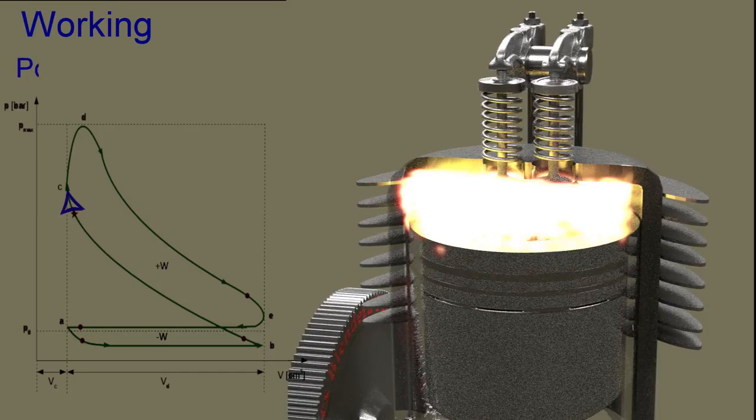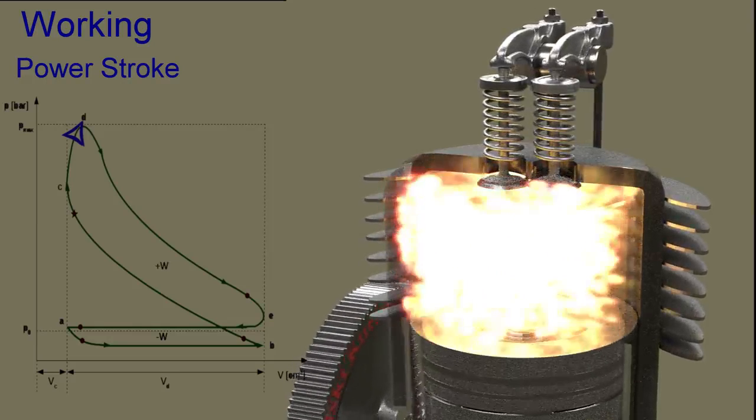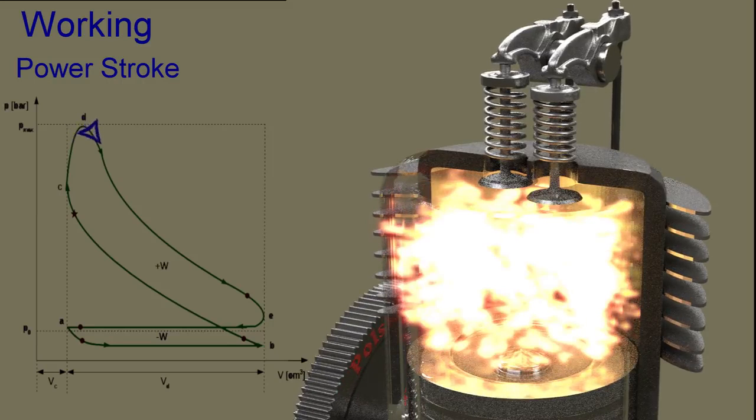Unlike the diesel engine, the combustion process in spark ignition engine is for very short period of time and therefore the piston has very small movement during the combustion. Therefore, the volume of combustion chamber practically remains constant and thus heat addition process can be approximated as constant volume process in petrol engine. Due to the rise in pressure, the piston is moved down with great force and hot gases expand. Thus, work is done on piston by flue gases and some of the heat is converted into mechanical work during this process.